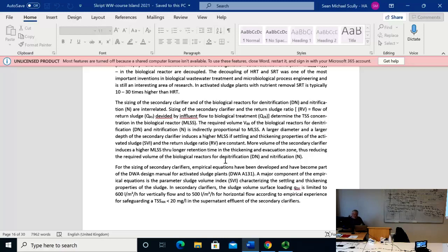The amount of food is determined by the inflow. You have an inflow of wastewater and you have a concentration. So this is the amount of food as kilograms of COD per day, which is the organic load to the biological system. Now, if you have a maximum allowable food to mass ratio, then you will have a required amount of microorganisms needed for totally metabolizing this food.